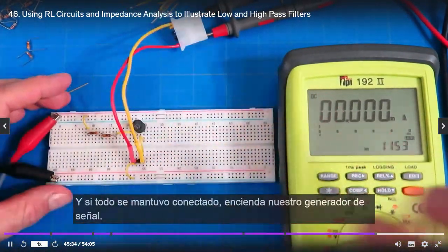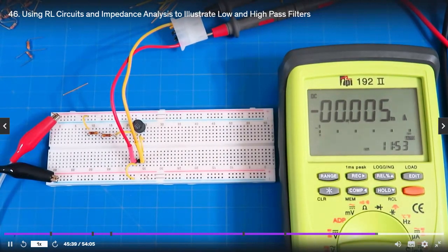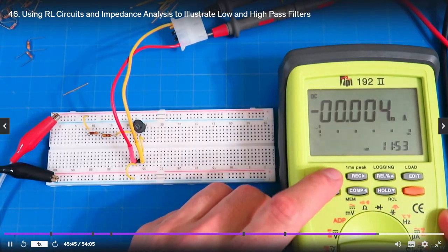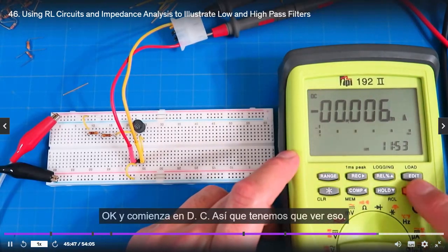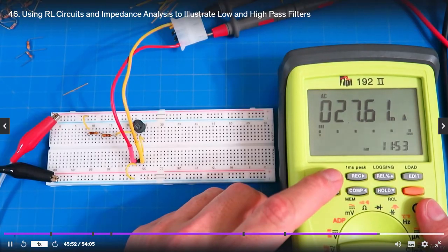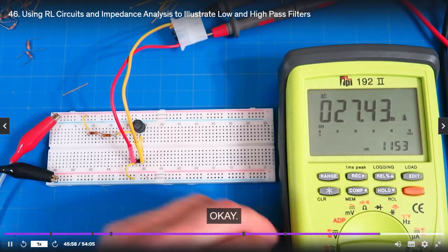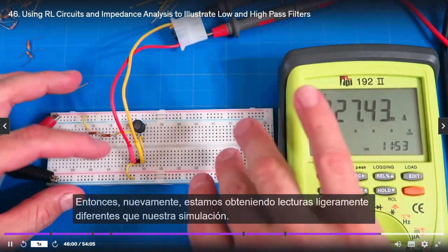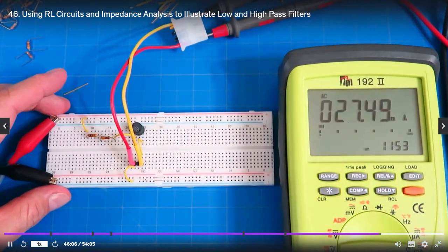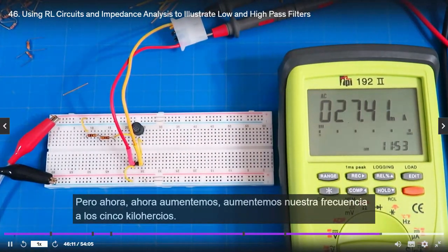And if everything stayed connected, let's turn on our signal generator. All right. Okay, and let's change the range here. It's starting off on DC, so we've got to put that to AC. All right, there we go. Let me play with the range a little bit. And it's showing the current as a little bit less here. So again, we're getting slightly different readings than our simulation and our math, and that's in large part due to this meter. Okay, but now let's increase our frequency to 5 kilohertz.